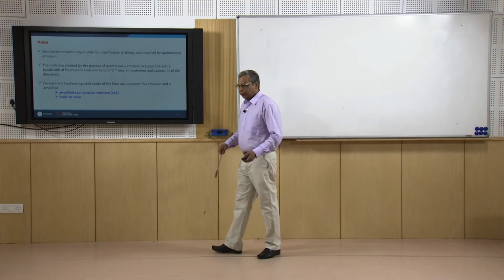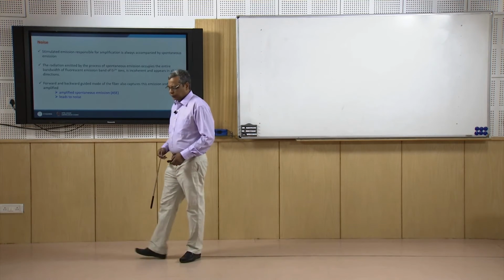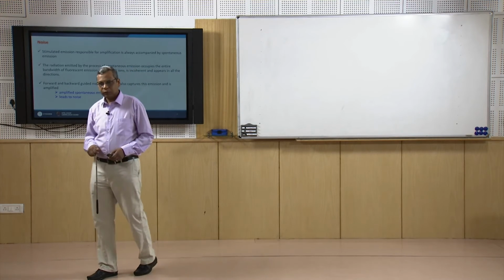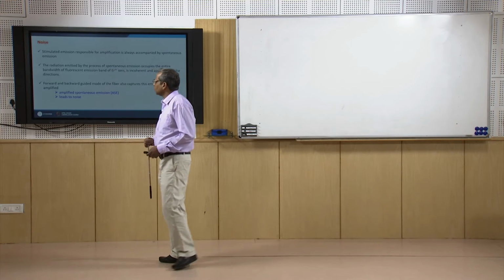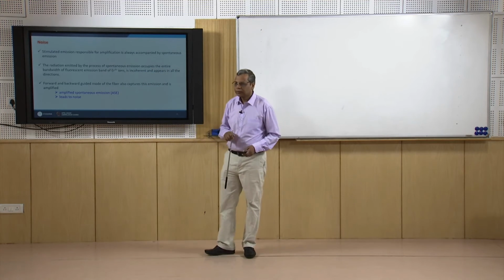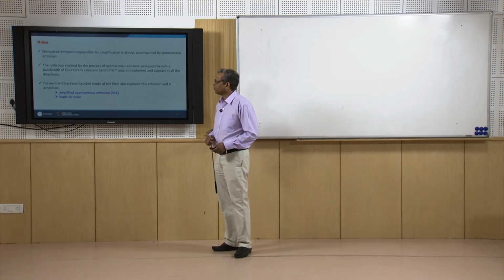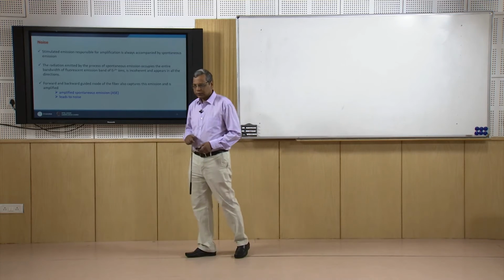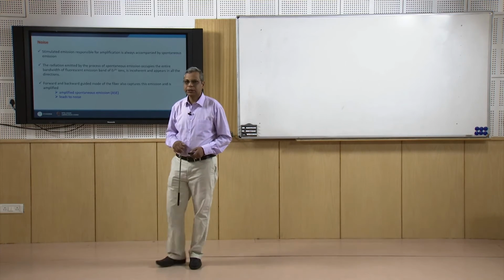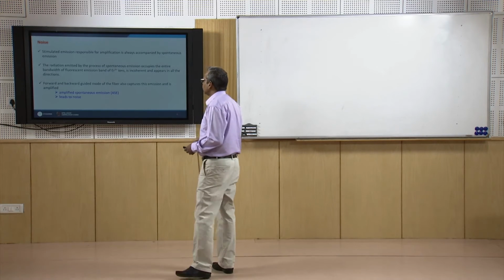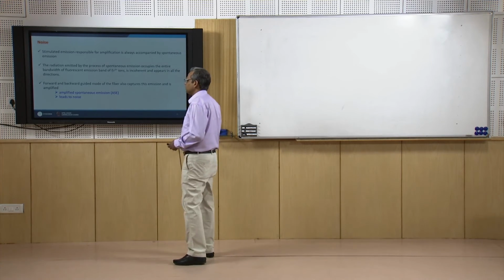Then along with the amplification of the signal, this amplifier also adds some noise. What is the noise added and what is the basic phenomenon behind the generation of this noise? Since amplification is provided by stimulated emission, and whenever there is a stimulated emission, it is always accompanied by spontaneous emission.